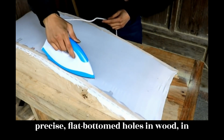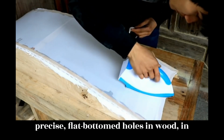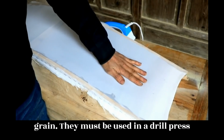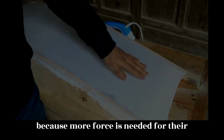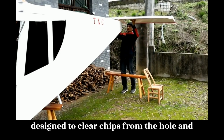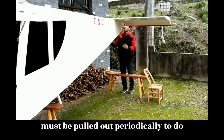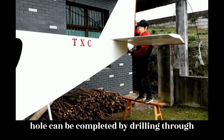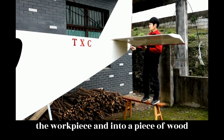Forstner bits bore precise, flat-bottomed holes in wood, in any orientation with respect to the wood grain. They must be used in a drill press because more force is needed for their cutting action. Also, they are not designed to clear chips from the hole and must be pulled out periodically to do this. A straight, accurate bore-through hole can be completed by drilling through the workpiece and into a piece of wood backing